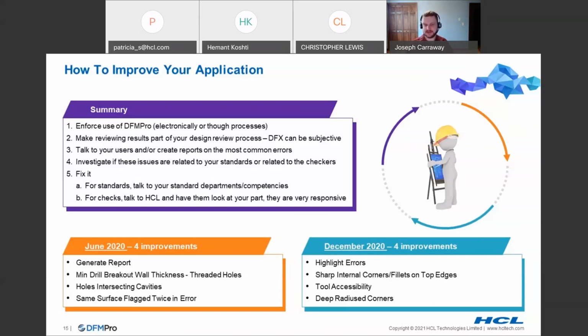There's a lot of discussions, even in my career, early on, there was a lot of, you have to have chamfers on the outside of a part, radius on the inside, never radius on the outside. But as technology progressed, those conversations are no longer nearly as applicable as they were 10, 20 years ago. Additive manufacturing is also changing this as well. So you can't apply manufacturing rules to additive manufactured parts. You have to have correct standards for these.